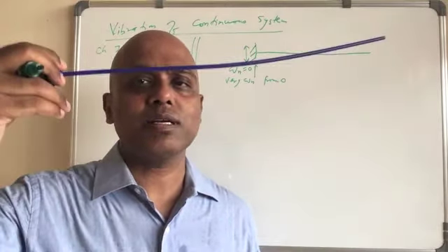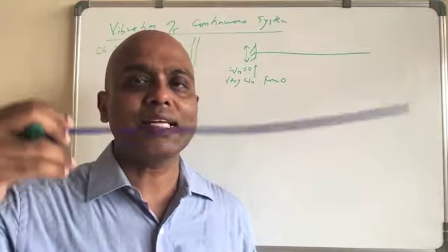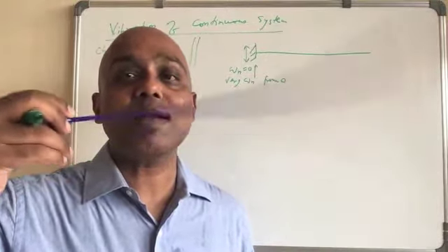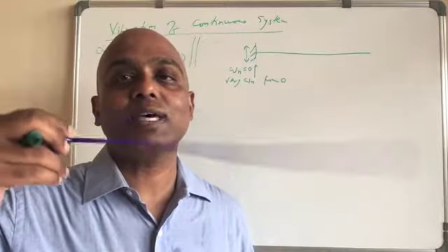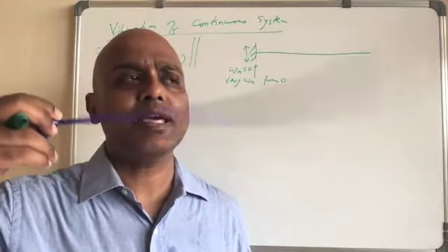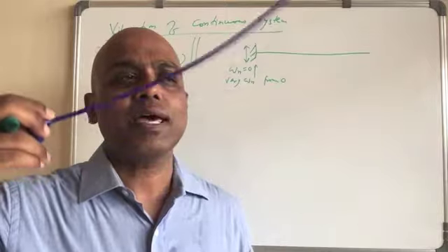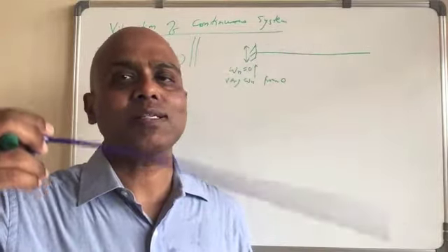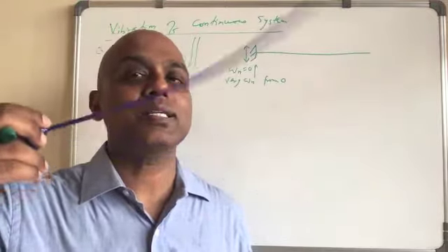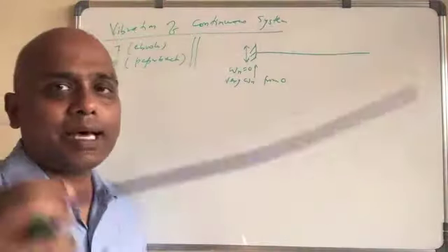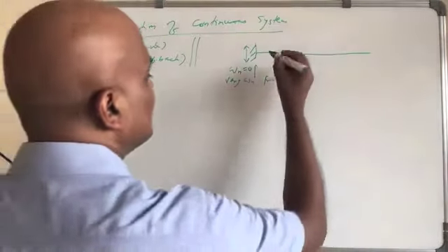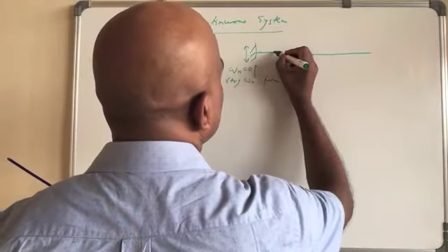Then you start increasing omega n slowly, and there will be one omega n where you get this vibration. What you are seeing right now is a kind of resonance at this frequency. So this must be its natural frequency, and this is the first mode.